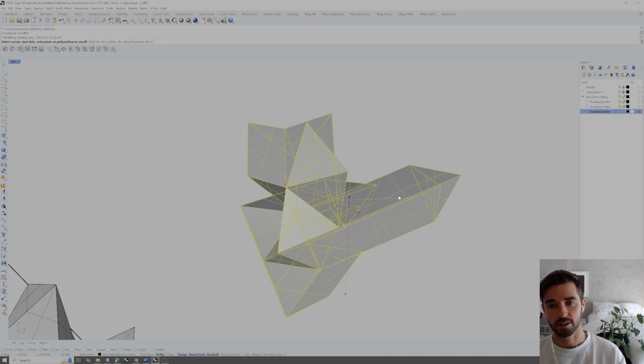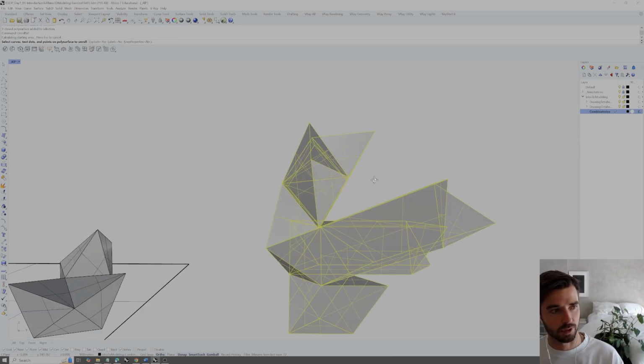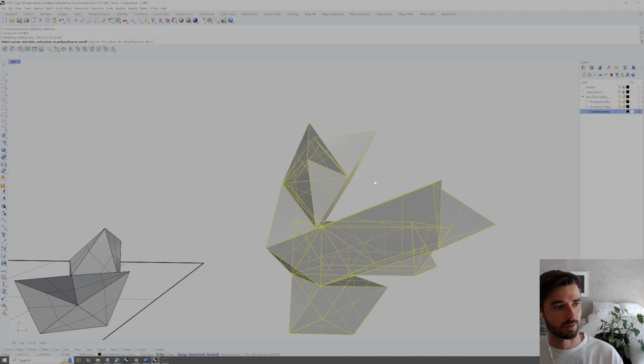It can do one axis incredibly easily, but it's not going to be able to bend in two axes without wrinkling or some deformation. And that's the same as this unroll surface. So it's going to basically easily unroll geometry that is singly curved or planar, but it's not going to be able to deform to unwrap any doubly curved surfaces. There are other operations that can do that, but they do have deformation, which means there is a change in the geometry, so it's not the exact undistorted version. So that's going to matter a lot when we get into fabrication methods and thinking about these types of things.